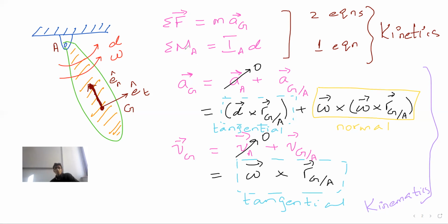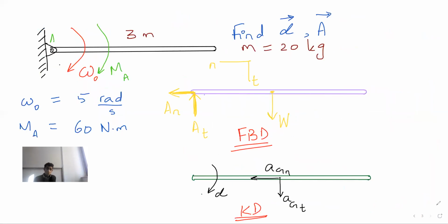If we have, let's say, moments about three different axes, you will have three equations from this. Are you getting my point? Summation of moment about the x-axis is equal to I subscript x times alpha about that x-axis, the summation of moment about the y-axis equals I subscript y multiplied by the angular rotation happening about the y-axis. Same story for z. And the same here, if the motion was in three dimensions, summation of forces in x, y, z, whatever. And we can have different coordinate systems for our own convenience.